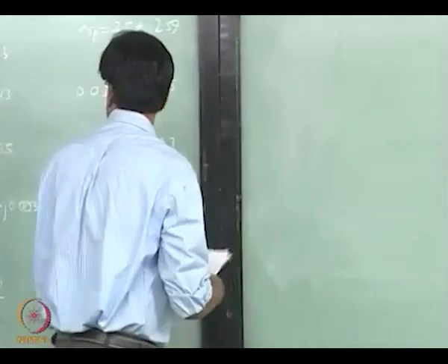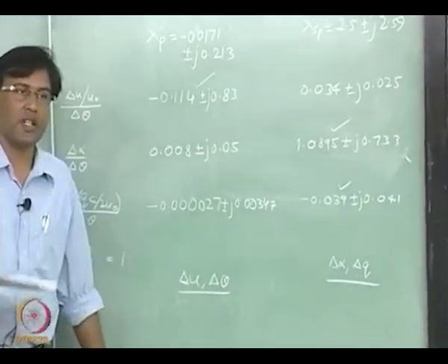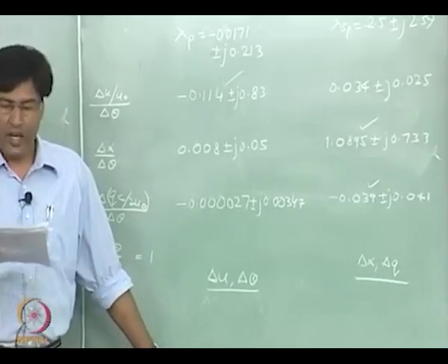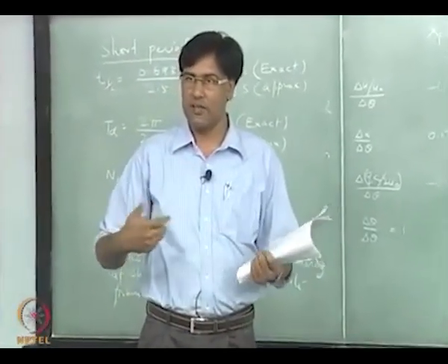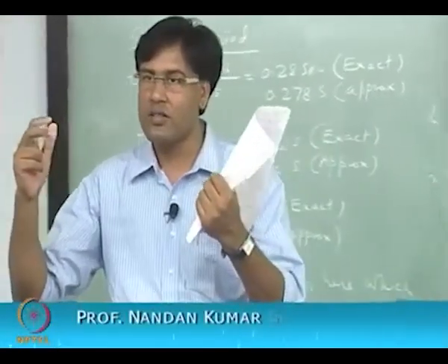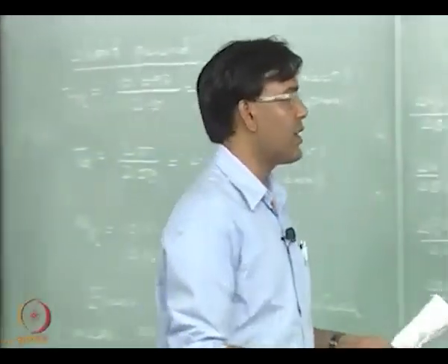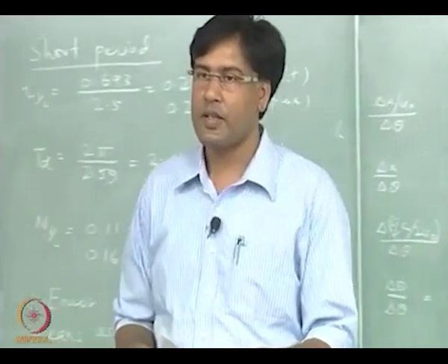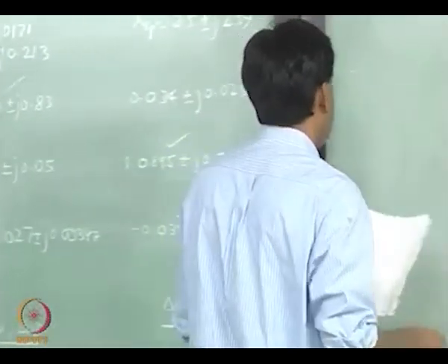Try to look at now the variation of these eigenvalues in the complex plane when you change something on the aircraft. One of the things that you can easily change is the CG. Sometimes there will be a block of masses just for balancing out the aircraft, so dead weights inside the aircraft which can be used to change the aerodynamic property, the stability property of the aircraft.